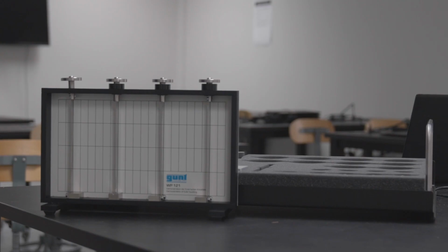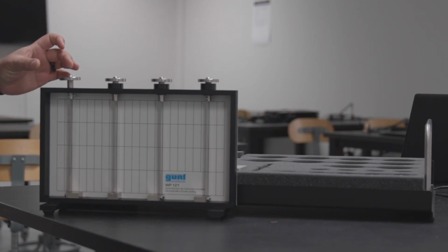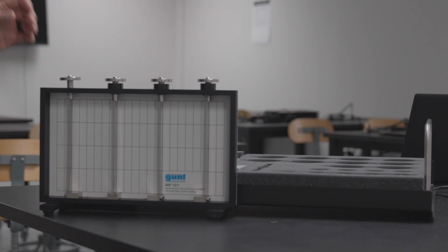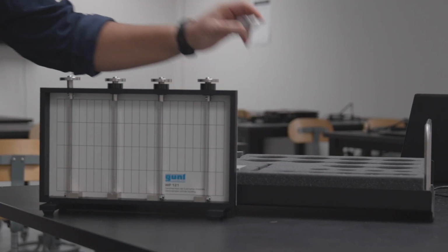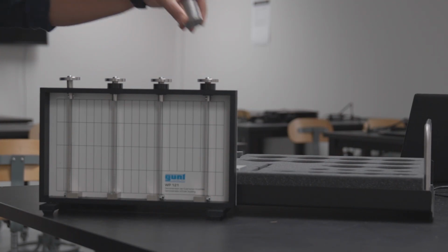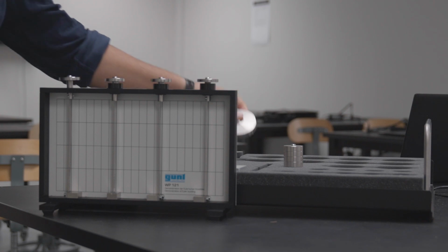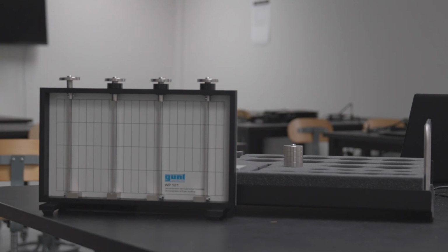In this lab, we are going to investigate how much these different supports are going to affect the load that is required for the buckling failure. So what we're going to do is add 1 Newton of load to each of these supports and just add another 1 Newton. These are the 1 Newton loads. As soon as your 1 Newton loads reach 5 Newtons and your column has not buckled, you are going to remove these 1 Newton loads and replace them with a 5 Newton load, right? And then you are going to record the load at which your column buckles.